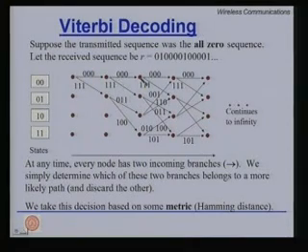If you proceed from here onwards, the next 3 bits are zeros. So, if you add to the metric 1 a 0, because no more addition took place, you still get 1. But along this one, you have 1 1 1, but the next 3 bits were 0 0 0, so the metric goes up by 3.